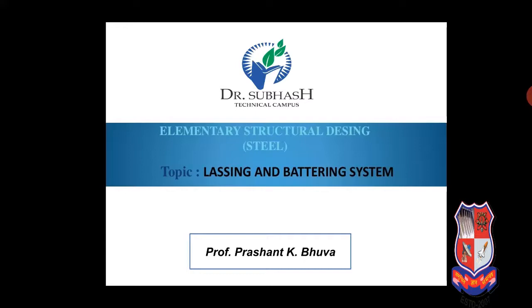So for large loads and efficient use of material, it is desirable to place rolled sections at some distance apart and interconnect them. The spacing and the orientation of the elements, meaning components, should be adjusted such that the slenderness ratio about both axes is the same. This arrangement of a column made of two or more components is called a built-up section.